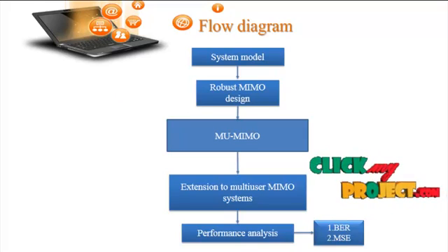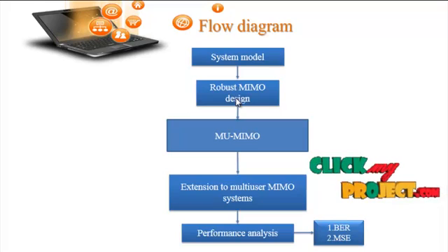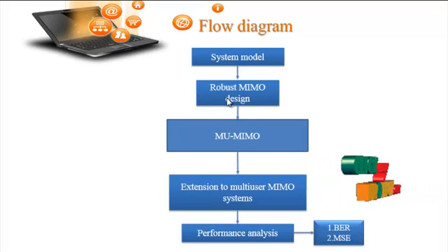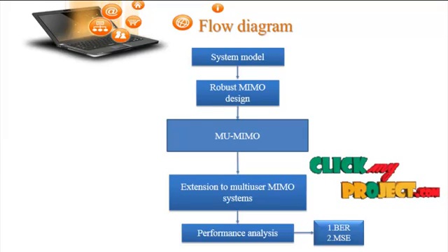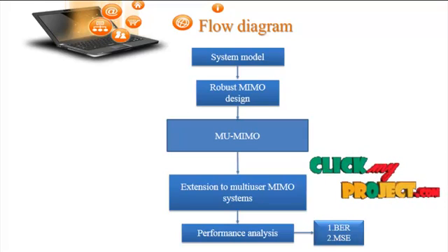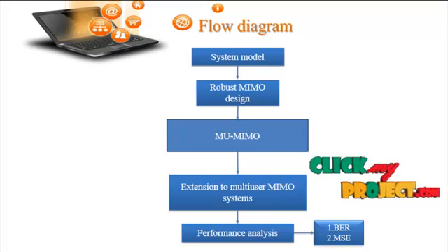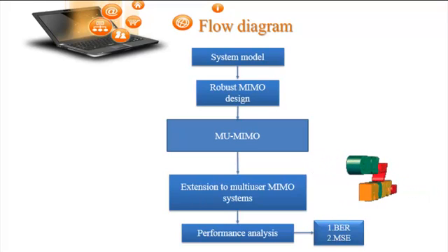The core is quantization at the base station of the massive multi-user MIMO. The multiple input and multiple output wireless system promises significant power and cost savings. Here we use the MIMO design of the system to convert the data that must be transferred from a spatially separated antenna array to the baseband processing unit. Operation over frequency-flat narrowband channels has been studied, whereas communication systems operating over frequency-selective wideband channels are less well understood.